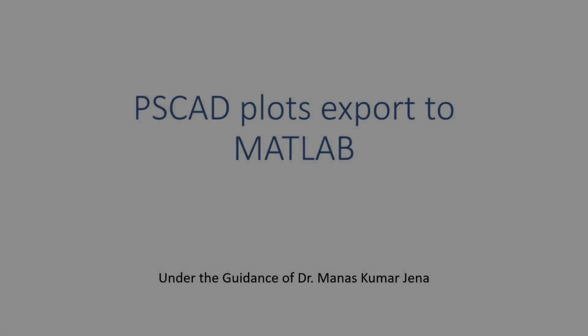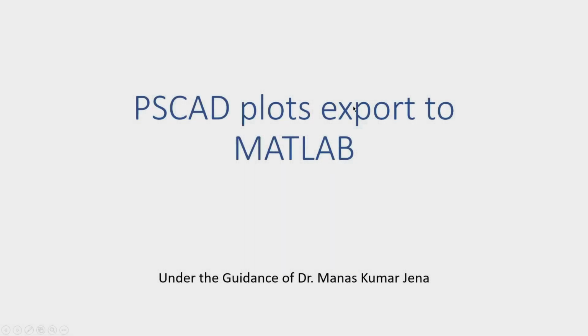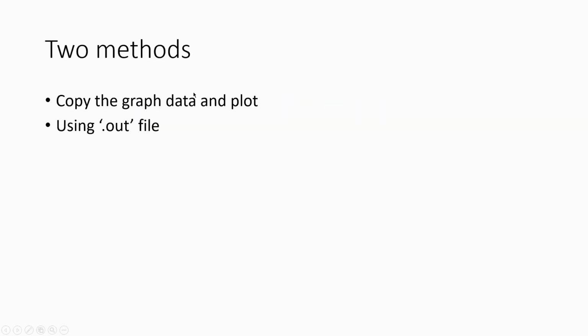Hello everyone. In this video, we are going to export PSCAD plots into MATLAB. There are basically two ways we can export the PSCAD graphs into MATLAB plots. One is by copying the graph data into the clipboard and plotting it in MATLAB. Another one is by using the .out file from PSCAD. We are going to see both methods.